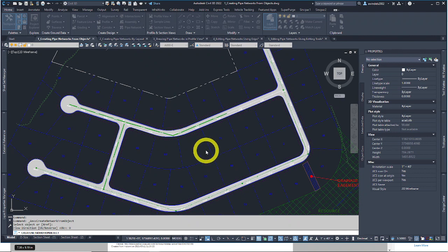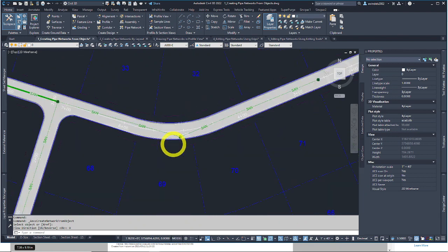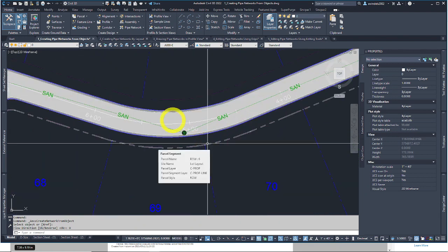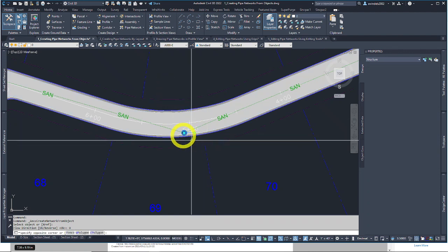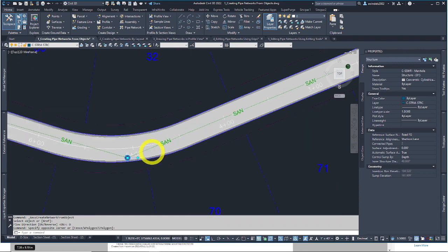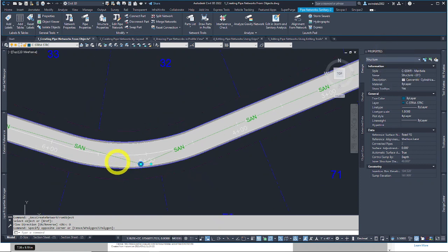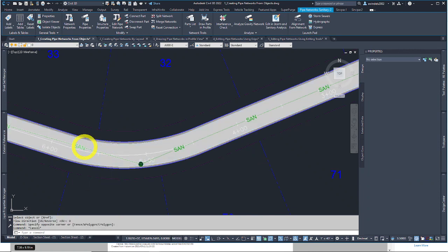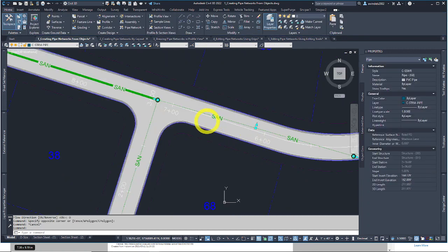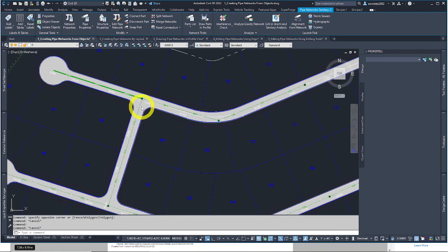Right. That pipe network is being made. You can see the objects appear now, and if you hover over one of them, or we crossbox over one, these points here are automatically created, these structures. So these are our pipe network structures we can see here in our Civil 3D properties, and we have pipes here. So our polyline is transformed into a Civil 3D object of various entities. So we got that going, and this runs down this way.